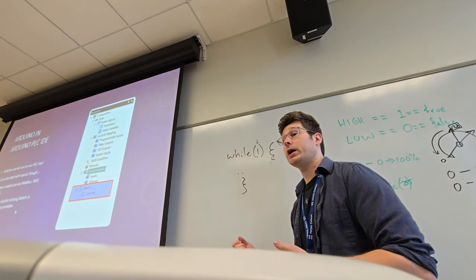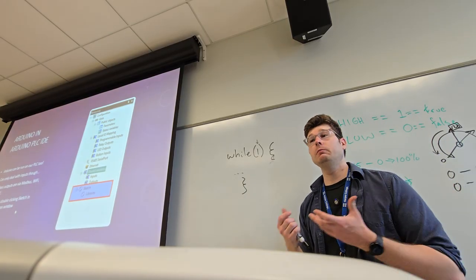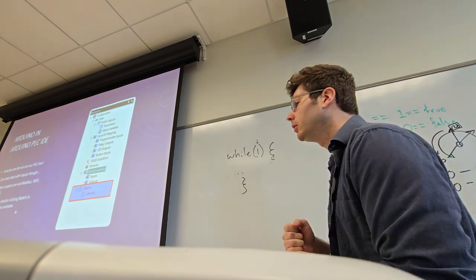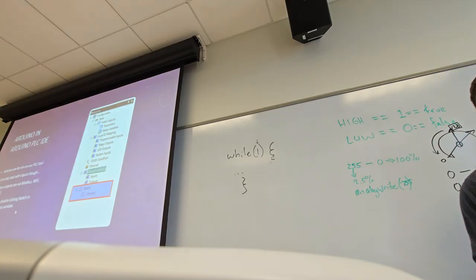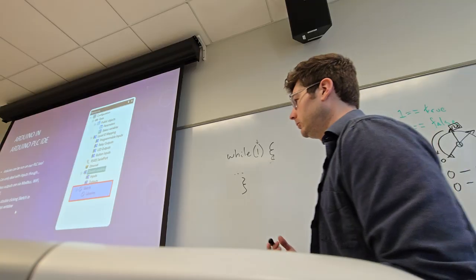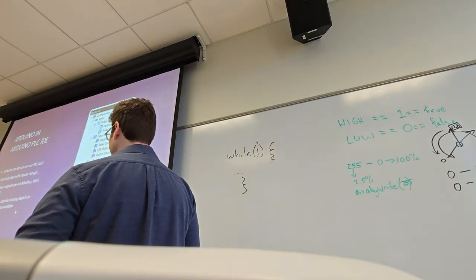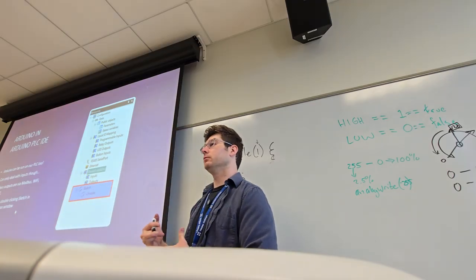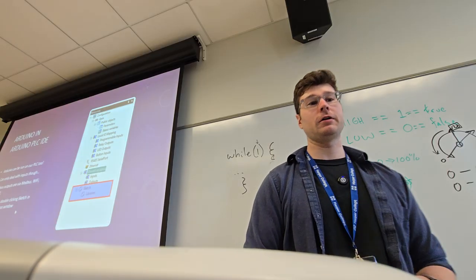You can use it to do logic. You can use it as like a math coprocessor if you want. But really the main thing that it's great for in terms of our PLC is communication. It talks Modbus, it talks Wi-Fi, it talks Bluetooth, all that good stuff. But otherwise it really is just a coprocessor to do whatever you want. It can share variables, it can control relays, it can read inputs to help out your main programs, you know, kind of more advanced functionality for your simpler, reliable stuff.